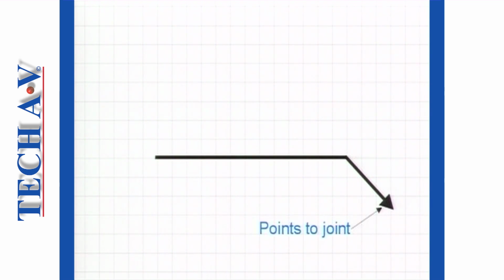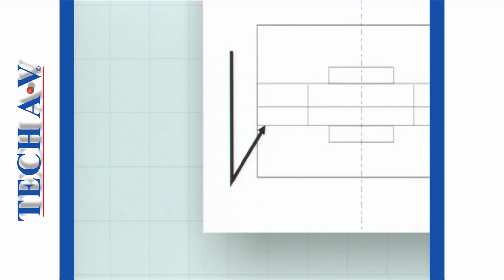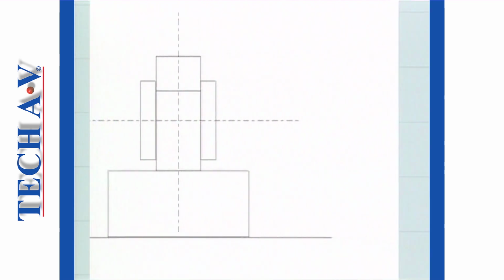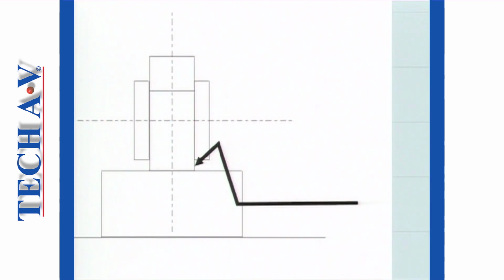The basic element of the welding symbol is a broken arrow, whose head points to the joint in question. The main arrow shaft is called the reference line, and is most commonly drawn horizontally. It is, however, permissible to draw the reference line perpendicular, if space on the drawing is limited. In this position, the symbol must be read from your left. When necessary, an arrow may even be drawn with a double break in order to bring your attention to a specific member of a joint.